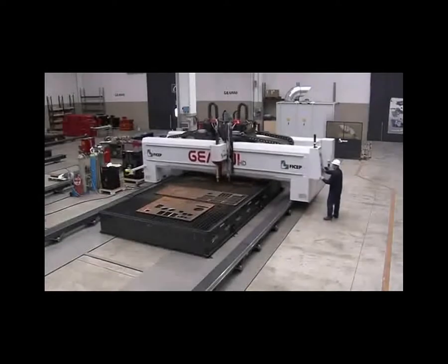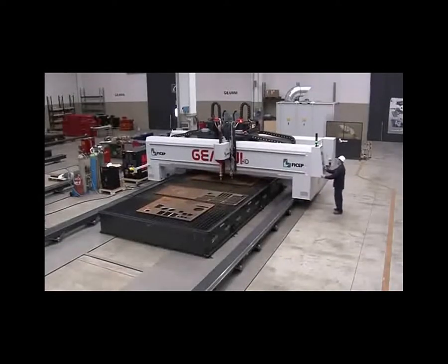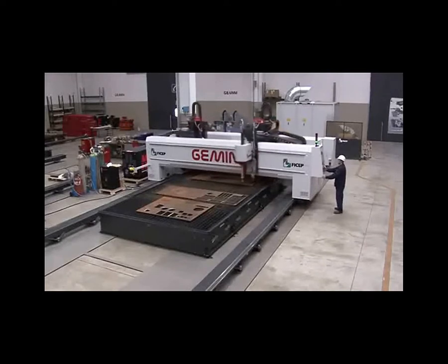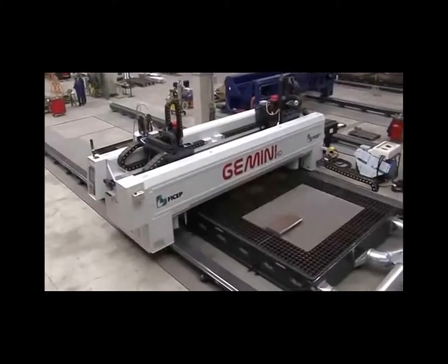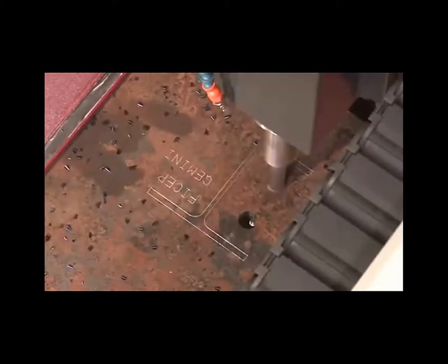Okay, so we've taken a look at linear elements to the machines, and the final one now is of course the plates. With the plate nesting, the information is passed directly down to the machine, in this case the Ficep Gemini. Just an example of how the machine looks. You can see the nested parts on the plates there, and the information of that nesting is passed through to the machine. Again, this can also be the layout marking, information on cutting, even including three-dimensional preparations can be done using this machine as well. Again, all passed through from the Tekla model.